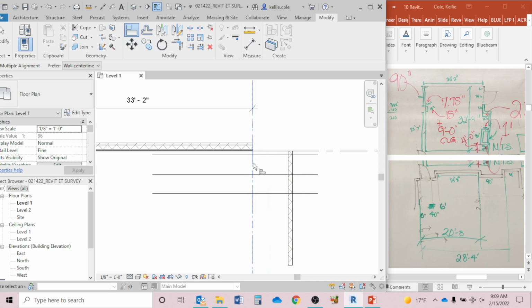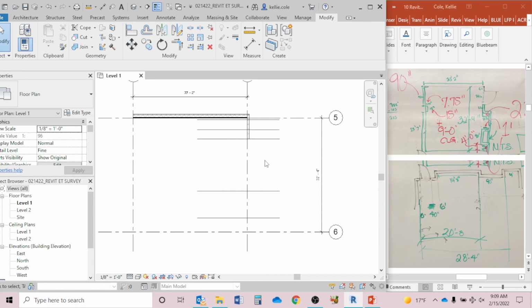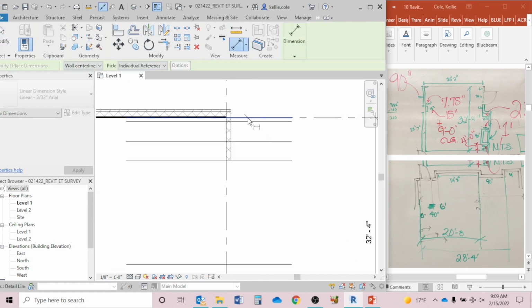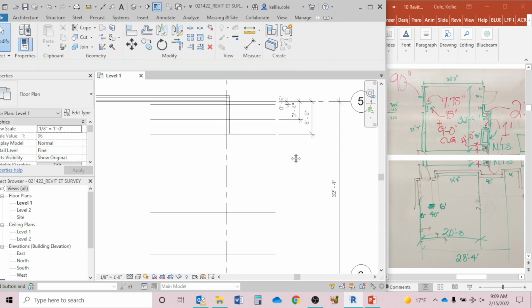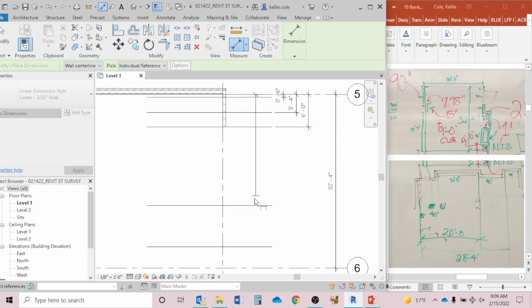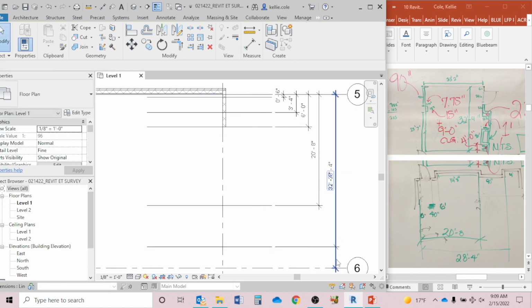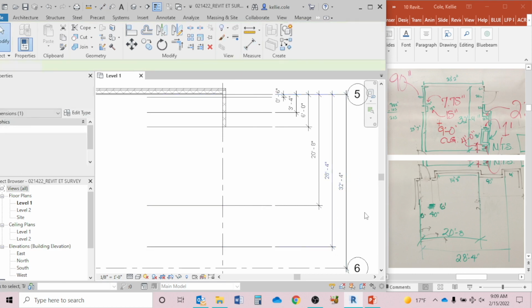Select the grid line. Yours is probably 4. And inside of the face, those walls automatically connect. And then let's align it to the 6 foot mark. 6 foot and back. I will dimension these here quickly, DI, so that you remember what each of the lines represent. I'm always going from the original line back. We'll move this one a little farther. All right, so those are all the copy or offset commands here.